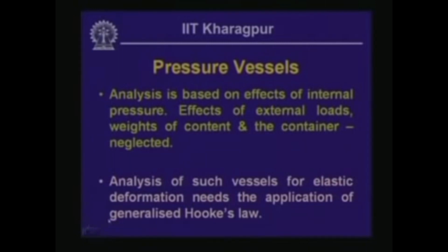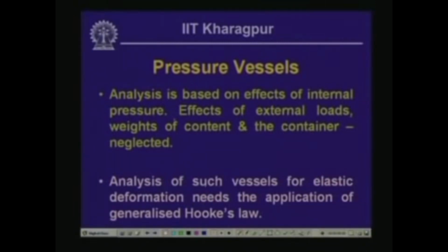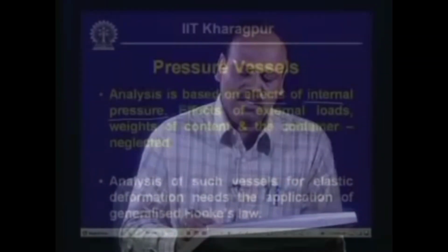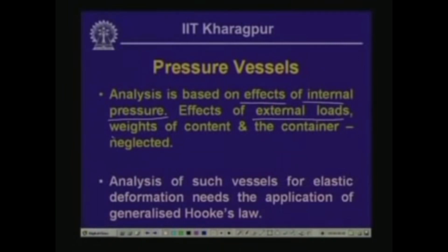Now, also in pressure vessels, when we try to analyze, we go for a simplified analysis, and this analysis is based on the effects that the internal pressure exerts, the forces on the body, and thereby the body is subjected to stress. That is what we try to analyze: how much stress the body undergoes when the container is subjected to pressure. But we neglect other effects such as the external loads, the weight of the content and the weight of the container. These aspects are neglected in this analysis.